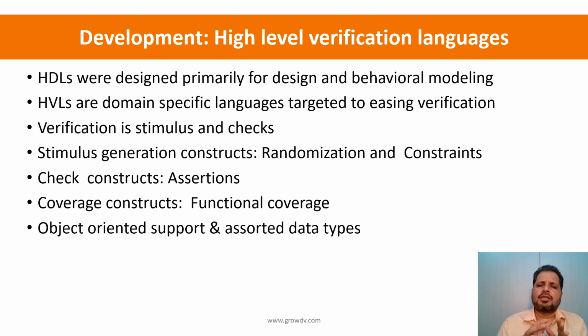However, assertions do not cover all the set of tests, all the set of checks that we need to do. For example, scoreboards are not implemented using assertions, right? For the scoreboards, we still use the behavioral modeling using the SystemVerilog code. And then there is this construct called functional coverage.